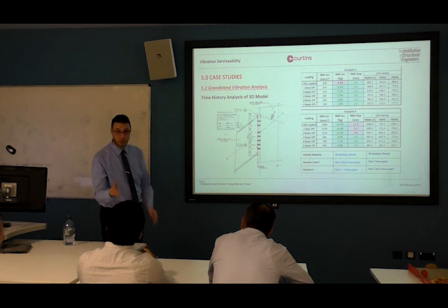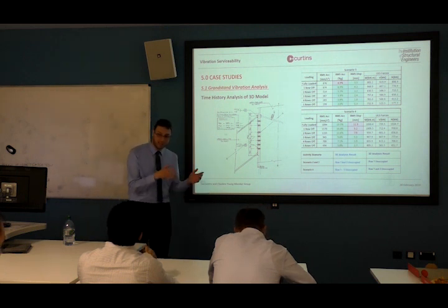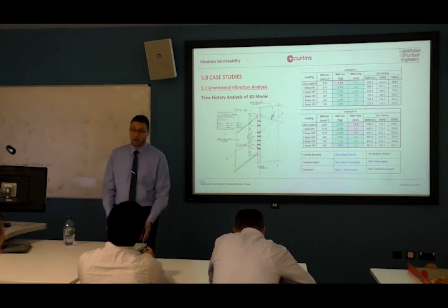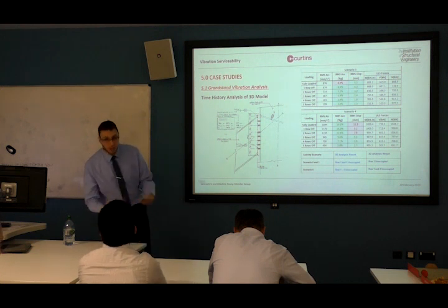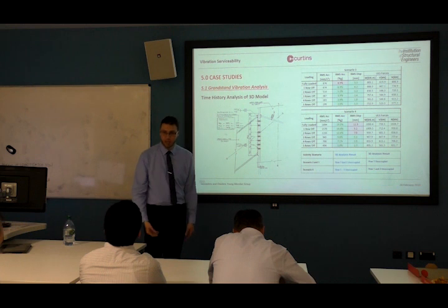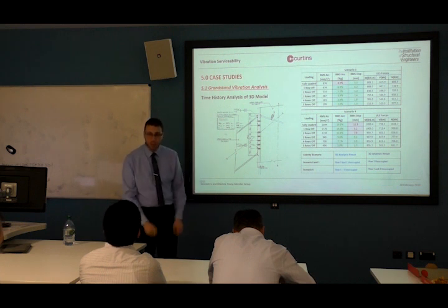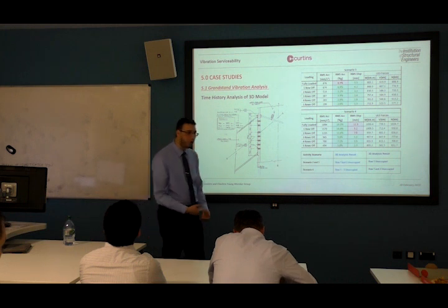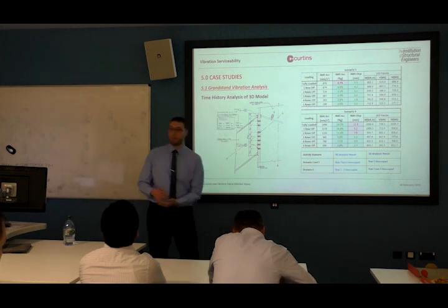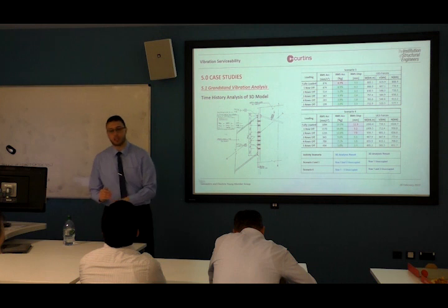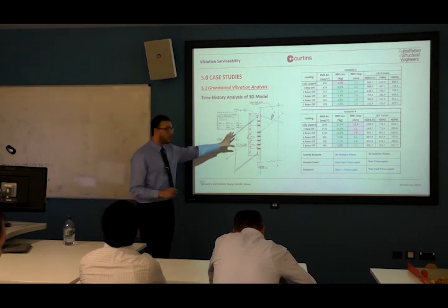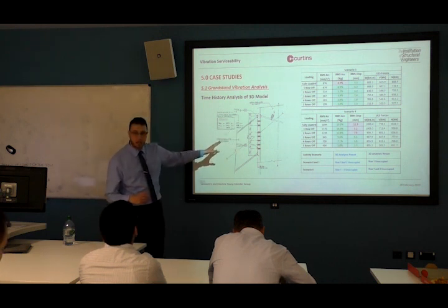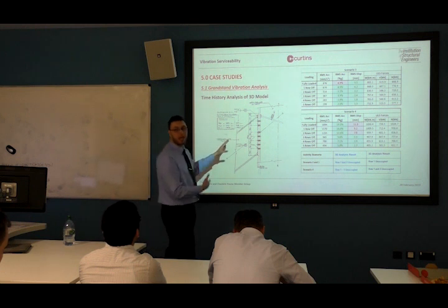So the case when you model it as rigid and when you model it as it is depends on how much load you have. So in walking, for slabs, yes, you're right, everything needs to be modeled as rigid because the amount of load will not exceed the small moment capacity of the connection. But this load here is quite high, and it needs to be modeled as it is.